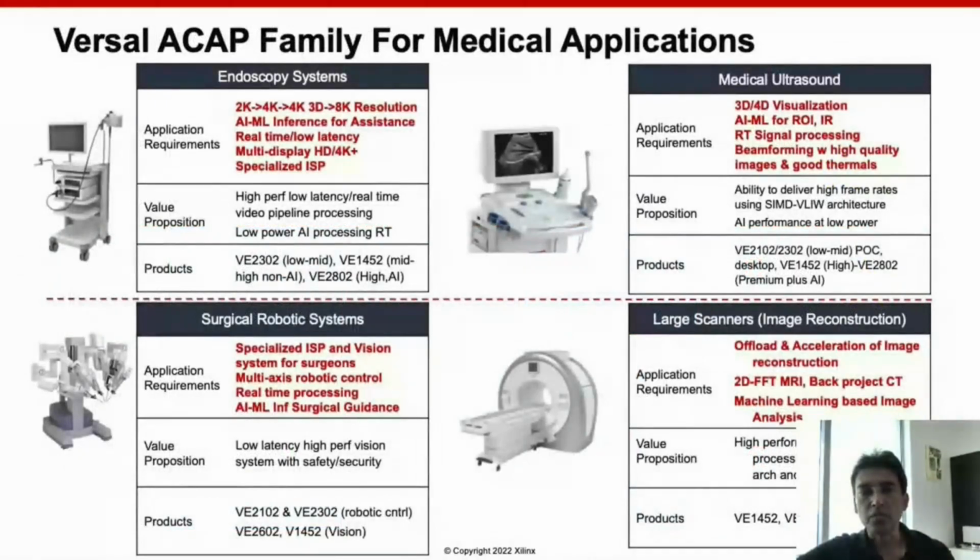So, delving a little bit more into the applications, you saw on a previous slide our newest generation of products in this 7 nanometer Versal family. Now, Versal is our adaptive compute platform with a closely coupled multiprocessor system, the programmable logic fabric, and the new intelligent AI engine with the highly parallel tiled SIMD VLIW architecture. SIMD stands for single instruction multiple data, and VLIW is very long instruction word.